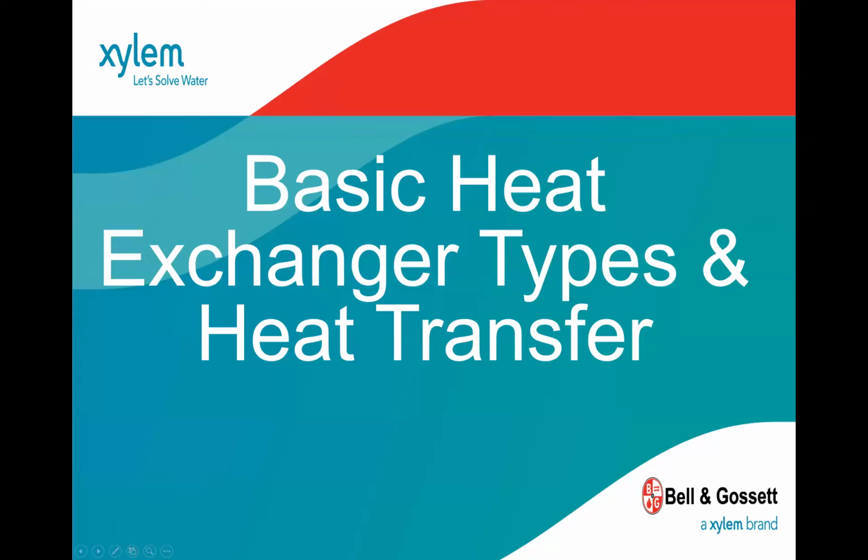But ultimately, let's see here. Let me skip out of these slides. So in this case, we've got the chilled water and the tower water. We have the entering water temperature 57, leaving at 53, 51, and 54. So in this case, we have temperature approaches of 3 and just over 2 degrees. What kind of heat exchanger would we use? If you have a very close temperature approach, would it be a plate heat exchanger?